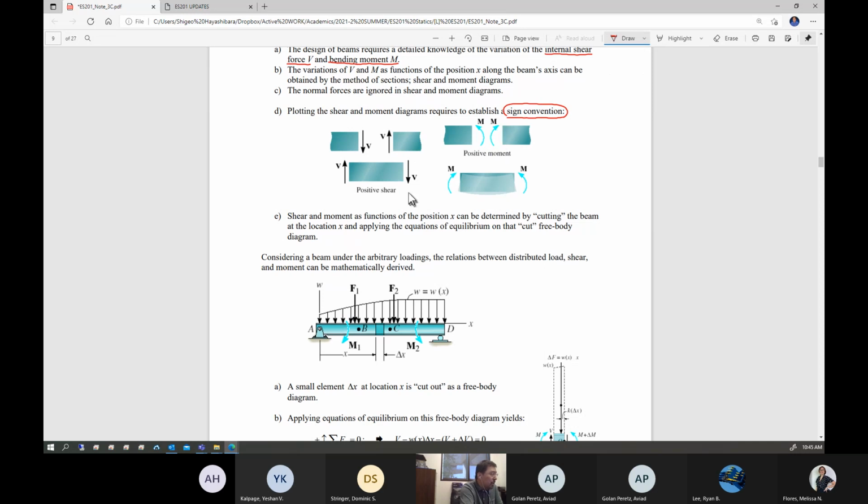If the shear or moment is applied at the end, okay, again, follow the same thing. Left-hand side is positive, right-hand side is negative. This is negative, this is positive. Right-hand side going down is positive. Left-hand side of the moment, this way is positive. Right-hand side of the moment, this is positive. So always, bending moment trying to bend this way is positive. Okay.